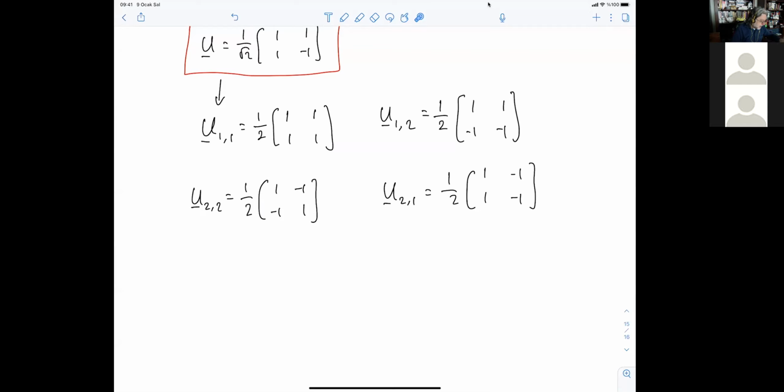And I'm not sure if I need to proceed any further regarding these optimum transforms. We can also talk about the singular value decomposition, which is another way of looking at one single image's best transformation, or image-wise best transformation. Karhunen-Loève transform is a one-dimensional transform. First of all, we have to be careful about that.